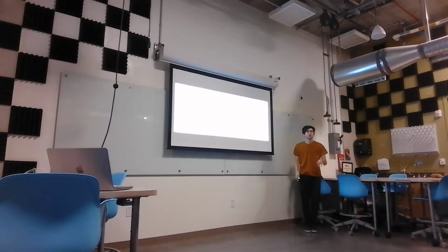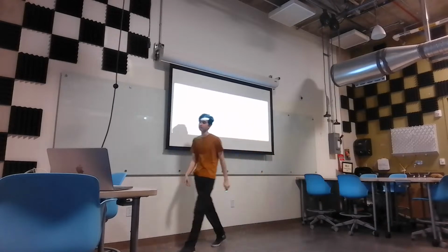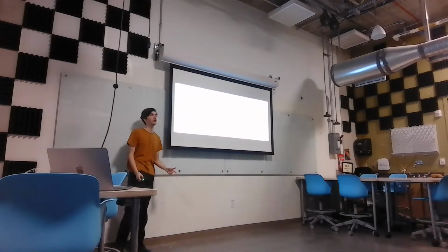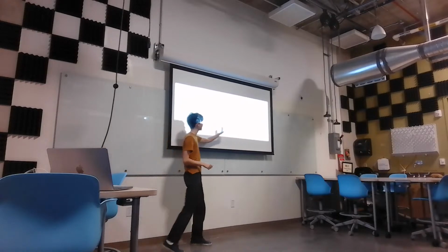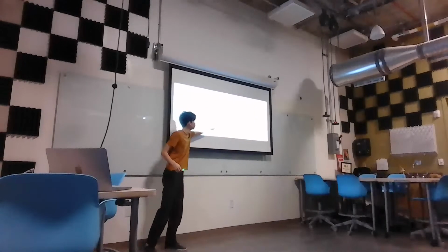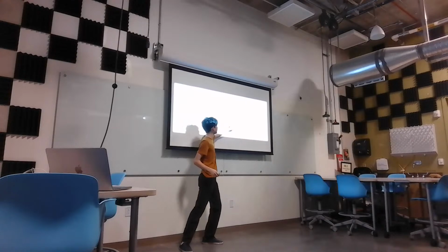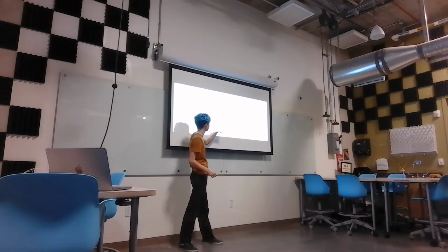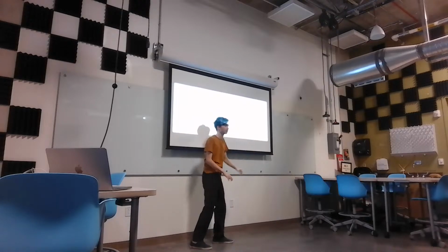Our first new design from the first hot one. Now what do we have? Microcontroller. Sick. What microcontroller? F0. Why? Because I heard of it and it was cheap. Next thing, gate driver. This puppy does this super cool thing where we just give it 2 PWM signals and it will output 2 PWM signals specifically for each FET. There's our bootstrap capacitor, which keeps this FET working when it's on the high side. Random capacitor stuff, output inductor, output capacitance.